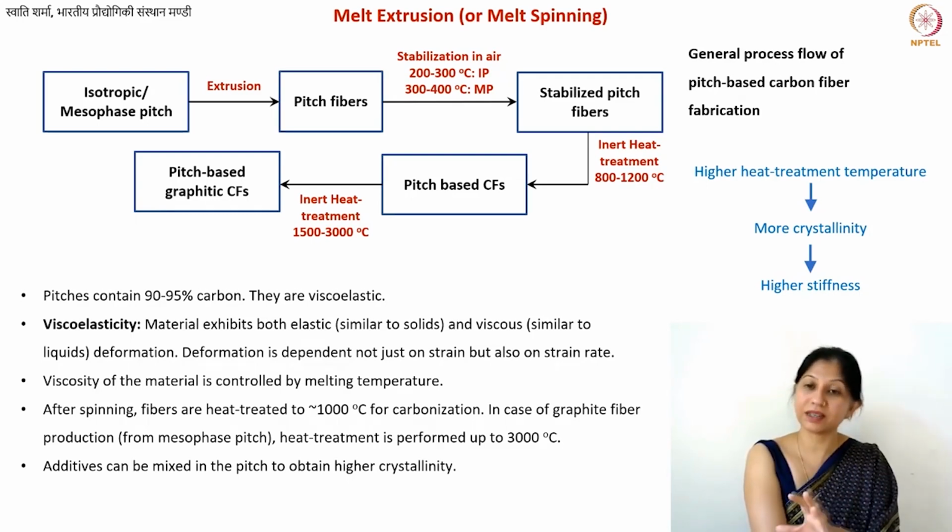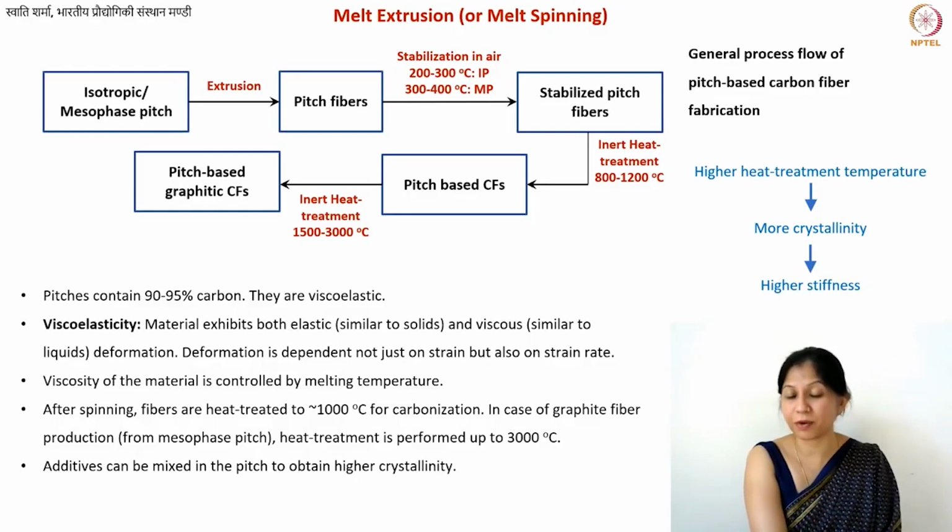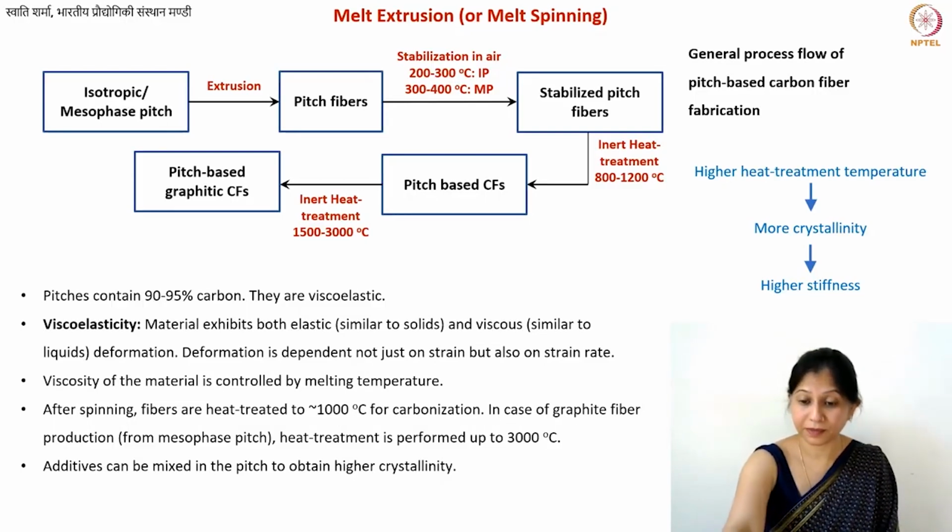Okay, so this is also valid for your fibers, and this becomes a very important property. Of course, industrially important, because for many applications, what you need is good mechanical strength. So that is why, same thing for carbon fibers, especially pitch-based fibers, the higher the heat treatment temperature, also that would increase the cost of the fibers. So this is basically a direct measure of the quality of your carbon fibers.